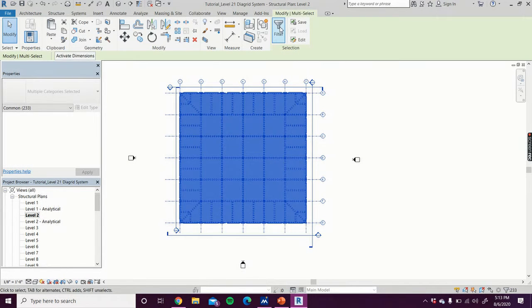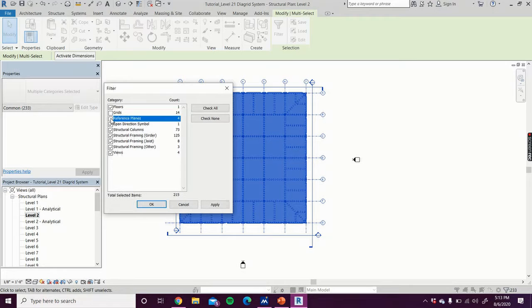This will basically just be the same process. Clicking floor and structural framing. You're going to see these different structural framing. If I haven't already adjusted this before, they're going to say girder, joist, other, or they could say other things. You can adjust that in your beam type properties, if you want them to be labeled a specific way, girder or joist. But as far as placing the beams, it shouldn't affect that, and you can always change it later. You're just going to have to select each beam and what type you want it. But for now, I'm just going to go back to copy and pasting.